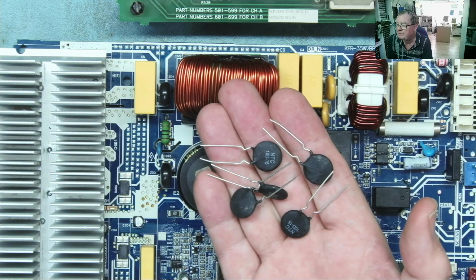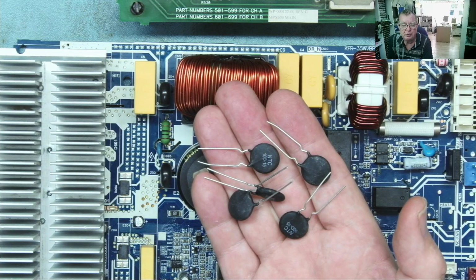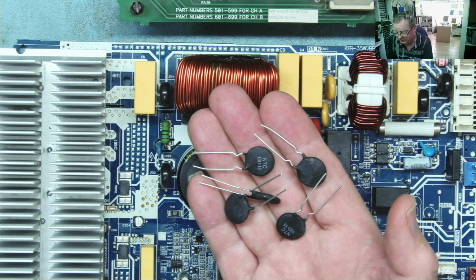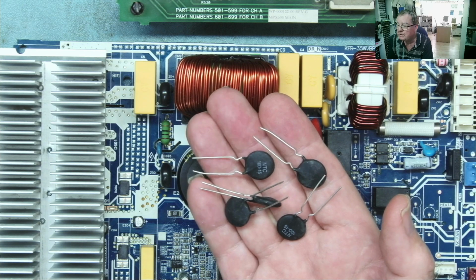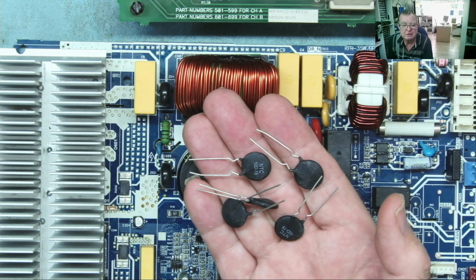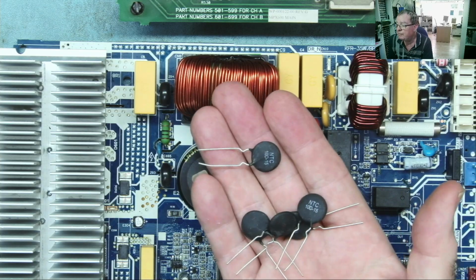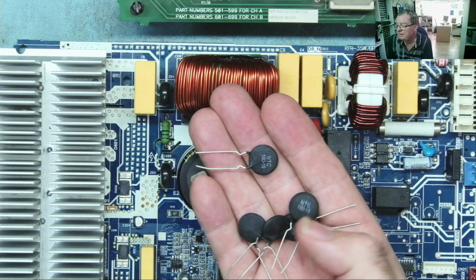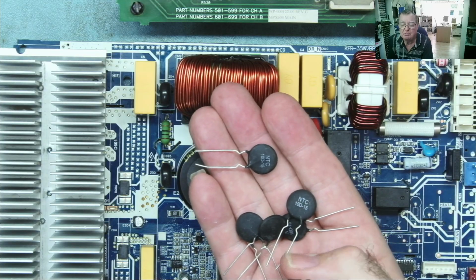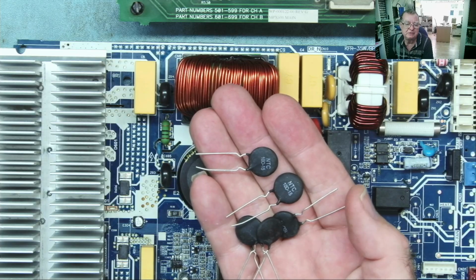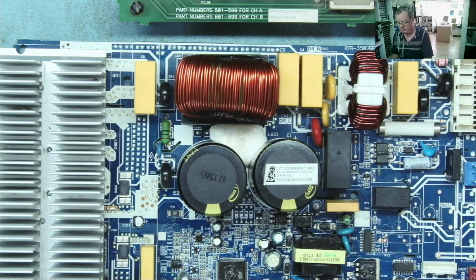These are devices that prevent too much current flowing into a device when you first switch on. So you're going to find these very near to the input of the circuit, usually before the bridge rectifier if it's a mains powered circuit. And these start off with a relatively high resistance, say 15 ohms, and then go down in value as they warm up. By starting at a relatively high resistance, they limit the current that flows into the device to charge, for example, the main capacitors.